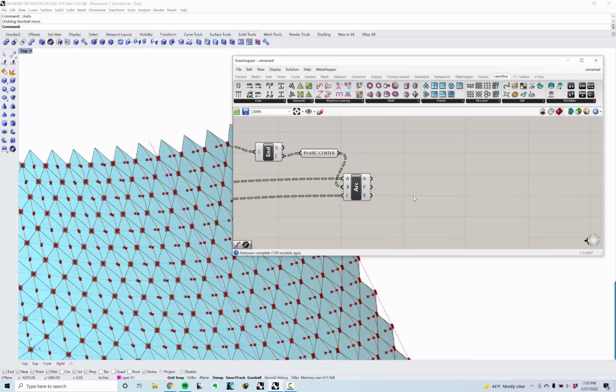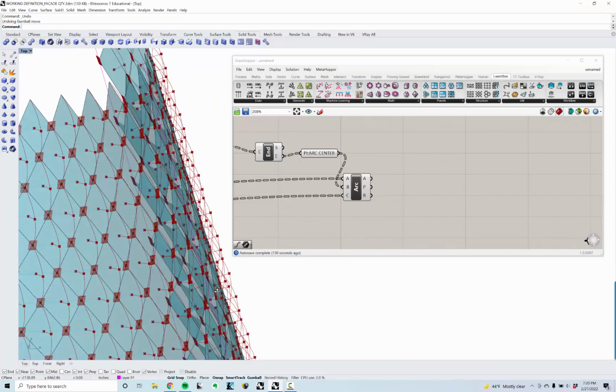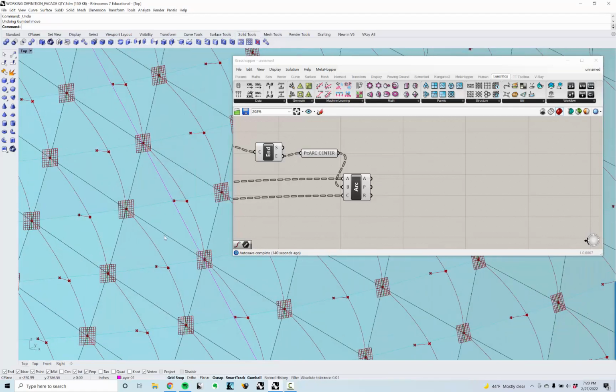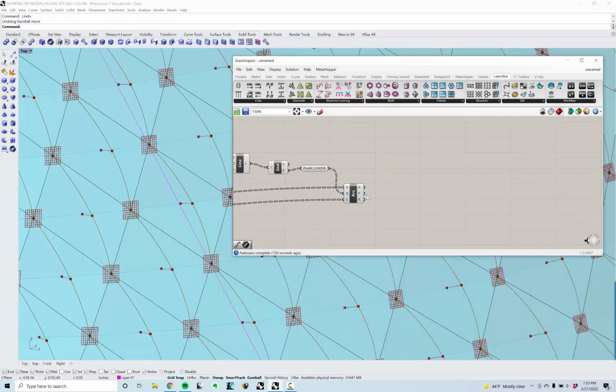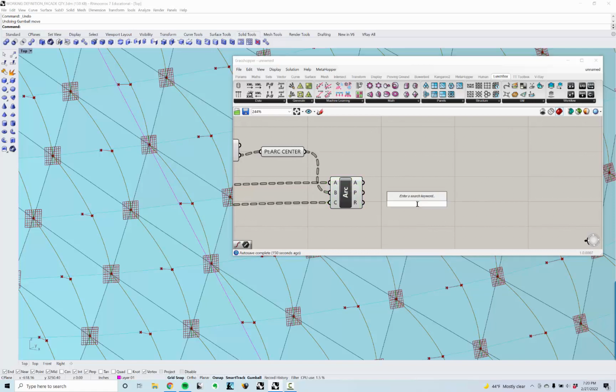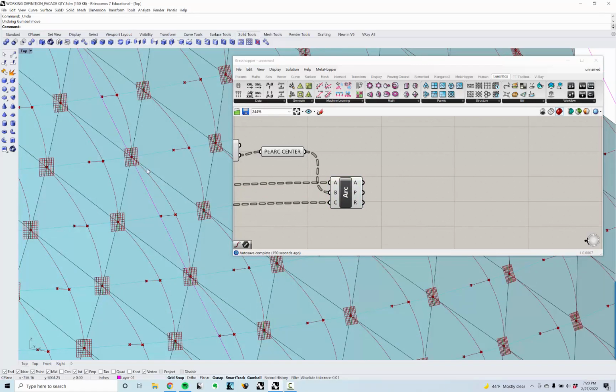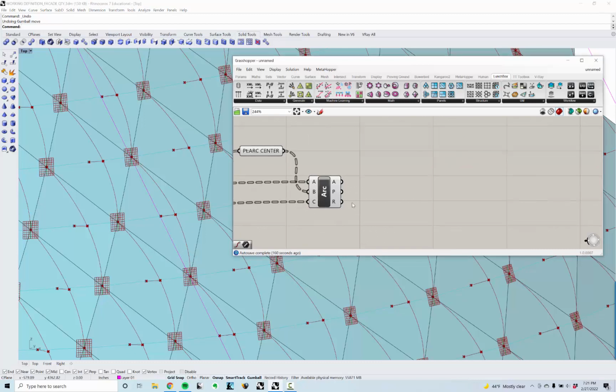Alright, so the next thing I'll do here is I'm going to start to construct the metal panel sunscreen that goes on top of this. And this is going to be easy. I want it to go from top left to the arc, and then top right to the arc. Again, it's just going to be constructed of triangles. So, oh, you know what? I'm sorry, I forgot one step. I want the point on this arc, which dictates where that sunscreen is, to change and be variable. So what I need to do is start to set up that logic, and then later we're going to plug in some values to make that work.